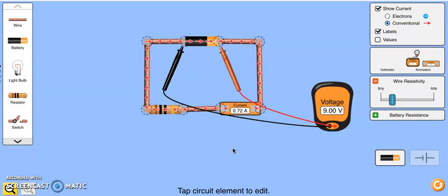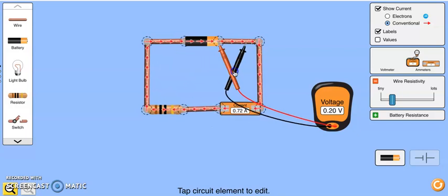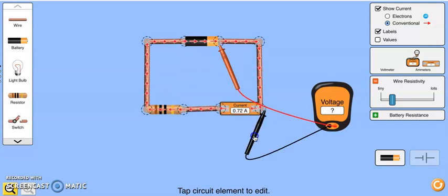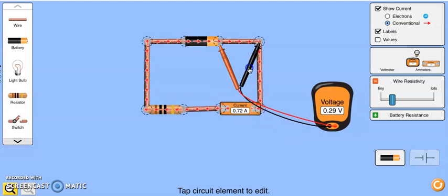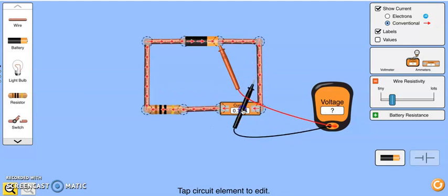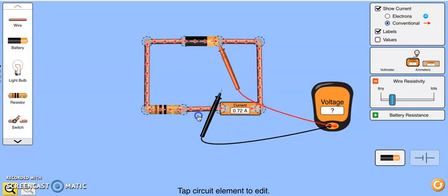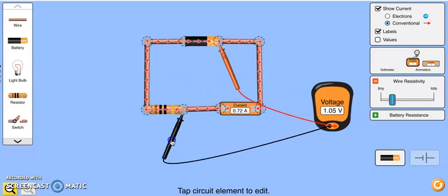All right, so the last thing I want to talk about is what we're going to do for a lab, and I'll lay it out on a sheet and post it on Schoology. We want to look at the relationship between voltage drop and current in a circuit. And you're going to do it for 2 different parts of the circuit. I want you to do it for 2 points from the positive part of the battery to some point along the wire. Okay, either this corner or this corner. Choose a corner. Actually, I'm going to change mine. We're going to do it here, just before we get to the load.